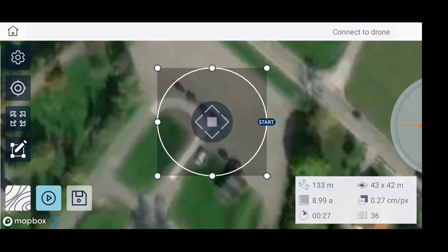And then click on play, wait another minute or two, improve the gimbal position if you need with the remote controller, rotate the drone a bit with the remote controller stick if you need, and let's say after 10 minutes you're more or less finished with data acquisition on the field for accurate 3D model generation.